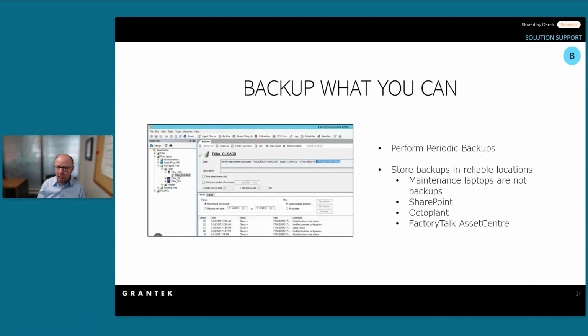Where it's got not only version control, but also verification features where you can schedule the system to take a look and say, hey, I'm going to do a nightly upload from every system and compare it to what's in the backup. Make sure it didn't get corrupted, the program didn't get lost, and it can email alerts and highlight things, like, hey, some welders were working down by line 7. They sent a surge up the power, and we lost that system, and you probably get the notification before production lets you know that things are down. And then you just go to Asset Center, get that backup, deploy it, and you're back up and running.